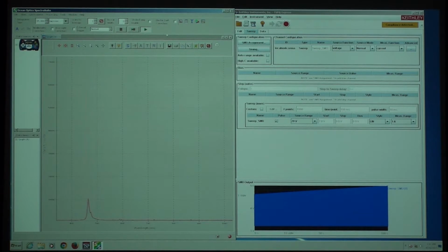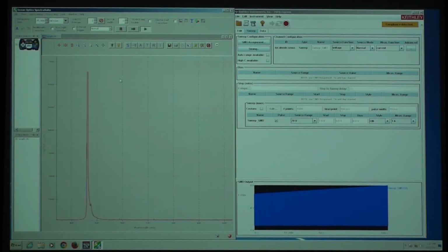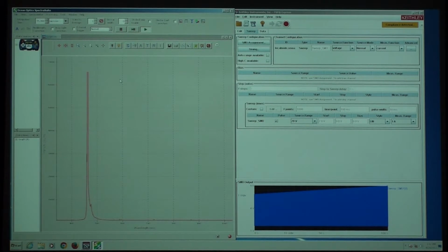Okay. So are you guys trying to change from spontaneous to stimulated? We just wanted to measure the peak, not to oversaturate. Okay, it's all right. Andrew? Just had a question about something I saw in the design. On the top contact, you have another heterojunction between InGaN and GaN. Is that just to make the ohmic contact with the metal?